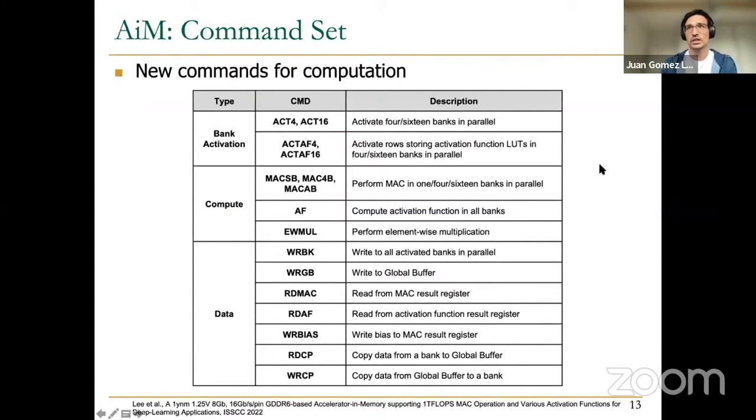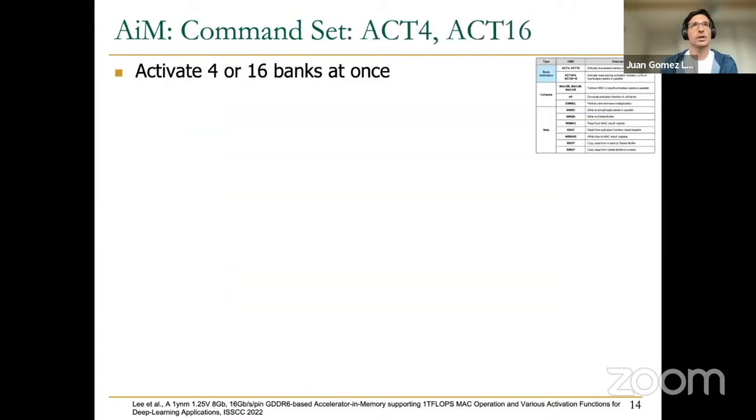to extend the existing GDDR6 commands. We will talk about some of these commands in a little bit of detail today, but here for now in the slide you can see this table where we identify bank activation commands, compute commands, and data commands. Actually, we start first with the bank activation commands.